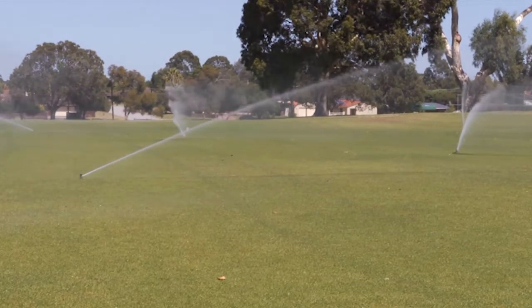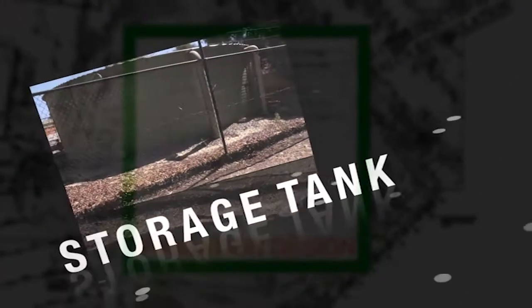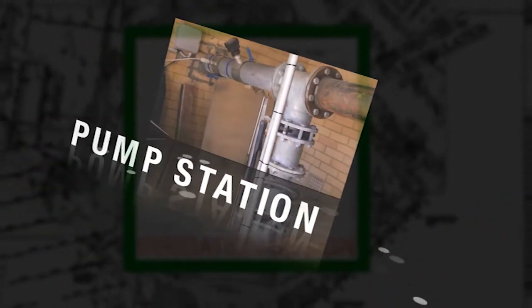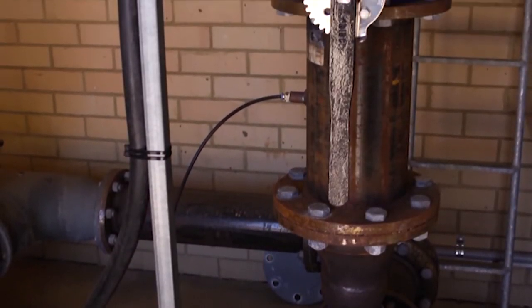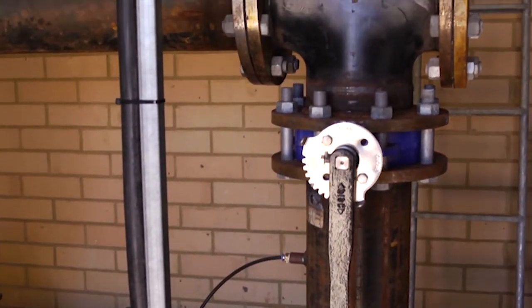The irrigation system at today's test site is supplied with groundwater. A bore pump discharges into a storage tank, from where an irrigation pump station distributes the water to the irrigation system. The irrigation pump is controlled using a variable frequency drive, which is an effective and efficient way to meet the varying needs of the irrigation system.